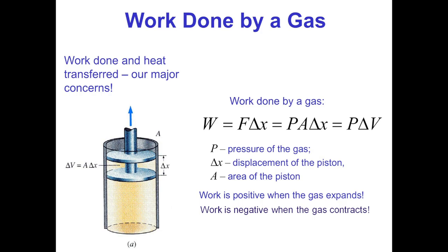It's another way that we can try to calculate the work that a system is doing. And again, it's based on one of the old formulas we already had. It is literally the same formula, just rewritten, kind of. It's the same information presented, just rearranged into different variables. Force was already equal to pressure times area, and delta volume is already equal to area times delta X.